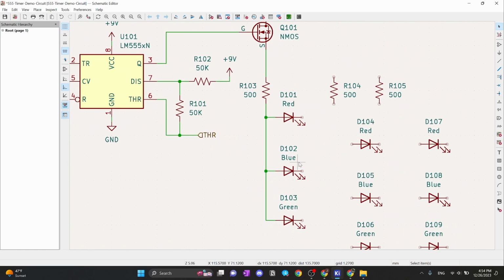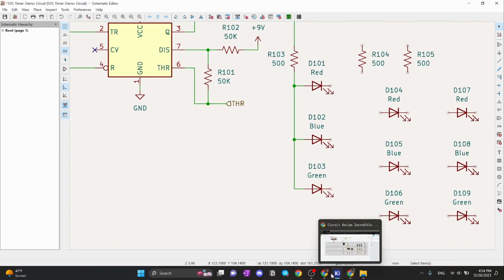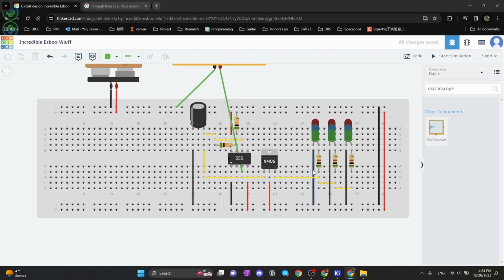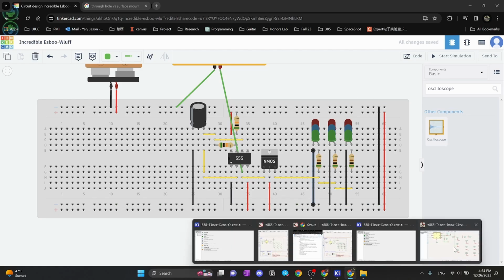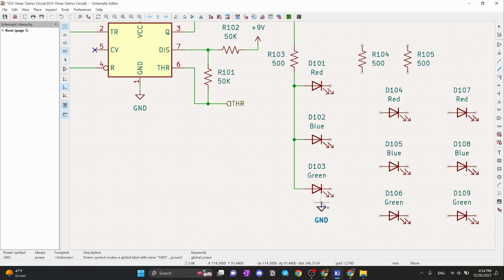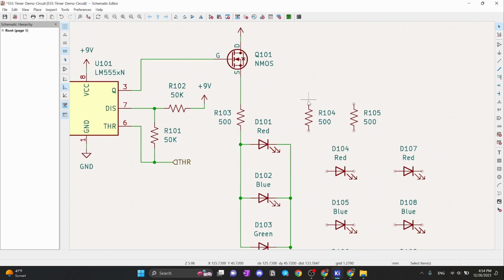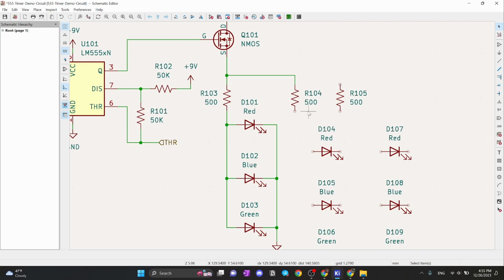All right. So again, all of them are connected to ground a little later. That's a ground connection, so we are going to need a ground. Again, Control C, Control V, and put it here. Left click, connect everything down. Like that. All right, and we have a few more resistors to place, but I think you already know how this works. Again, left click on the pin and drag them to here.